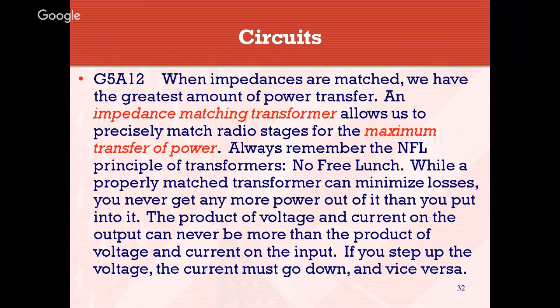And remember the NFL principle of transformers: no free lunch. While a properly matched transformer can minimize losses, you never get any more power out of it than you put into it. The product of voltage and current on the output can never be more than the product of voltage and current on the input. So if you step up the voltage, the current must go down and vice versa.